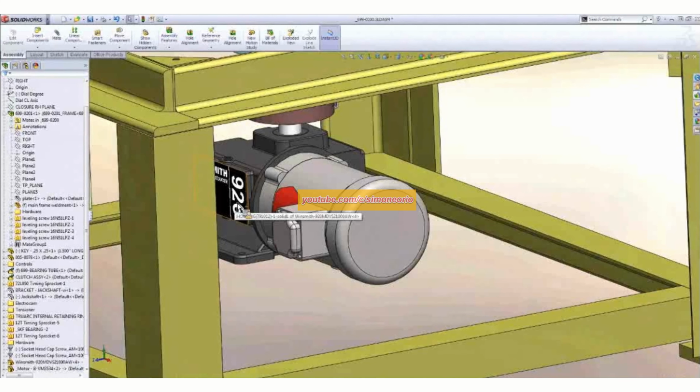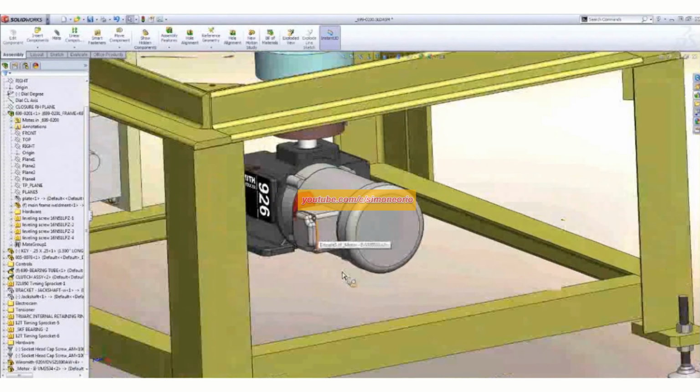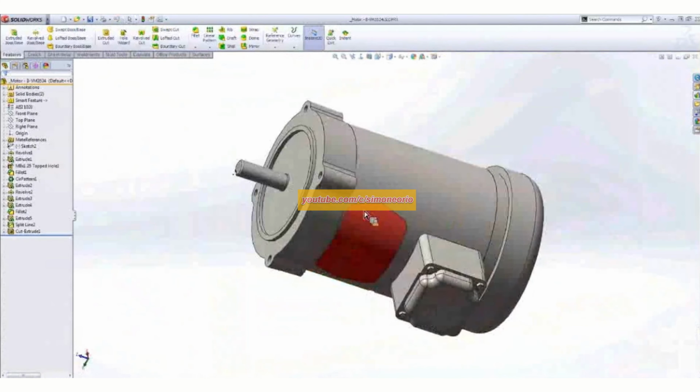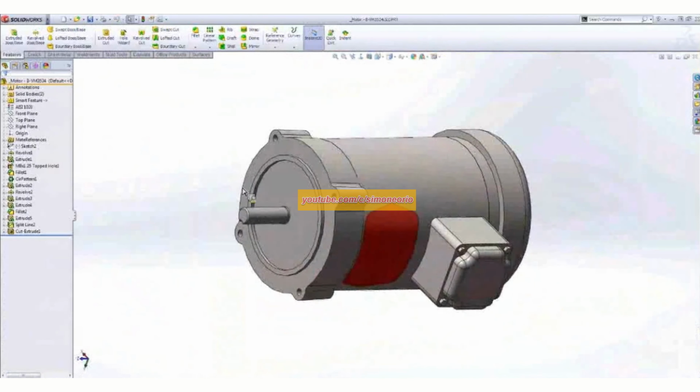This is a fully mated part. Literally all I did was a drag and drop procedure here. And really all I'm using is what's called a mate reference at the assembly level, or part level, really. And if I open this component up real quick, if you're not familiar with mate references, here's your education. But basically here inside of SolidWorks, you can build different mate references, and it's just like a smart mate that it's looking for. So when I drag it in the assembly, it's trying to go concentric or coincident or both, as an example. And that's what you can do here.